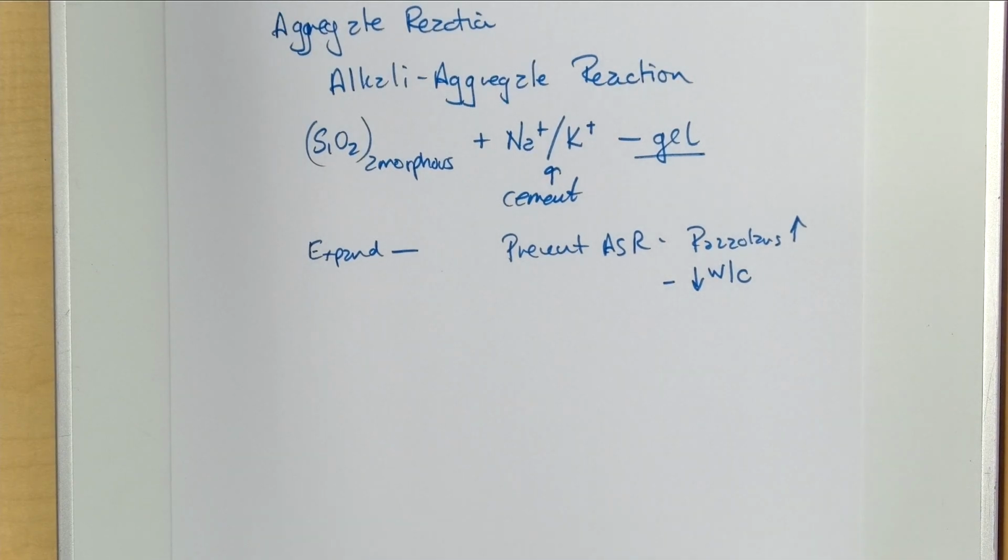And the reason we decrease the water cement ratio each time is because as the water cement ratio goes down, the space available inside the concrete that is not a solid goes down. That's why the strength goes up as the water cement ratio goes down. Abrams had no idea. We know this from other porous materials we developed mainly for the space program when we were sending people to the moon, which hopefully we'll do again. Only because they're going to have to build the moon base out of something, and that's not going to be steel, right? What do you build the moon base out of?